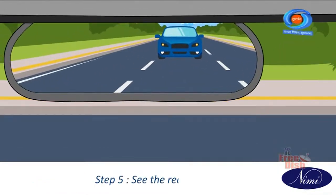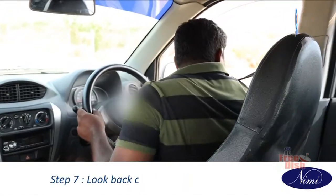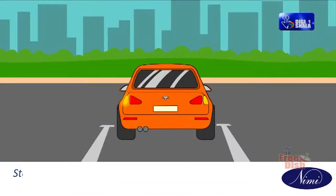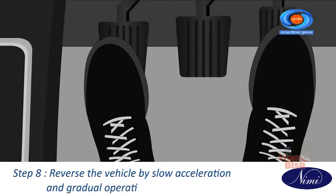Step 5. See the rear view mirror. Step 6. Sound the horn. Step 7. Look back over your right or left shoulder. Step 8. Reverse the vehicle by slow acceleration and gradual operation of clutch.